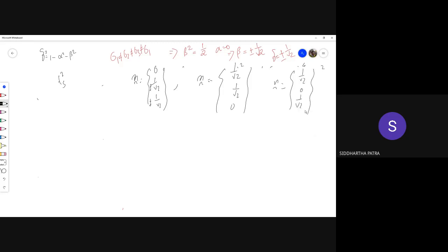Okay. So what does this mean? This means, first of all, I need to identify. So these are principal directions: n1, n2, and n3, and I'm looking for a normal to a plane in which the shear component of the traction is maximum, or TSS squared is the maximum.